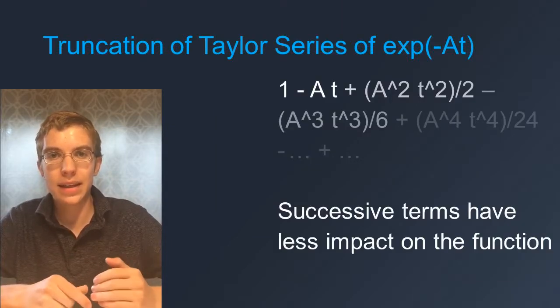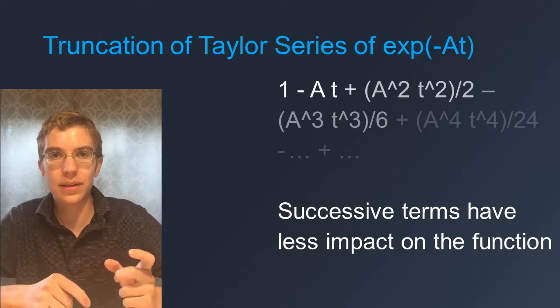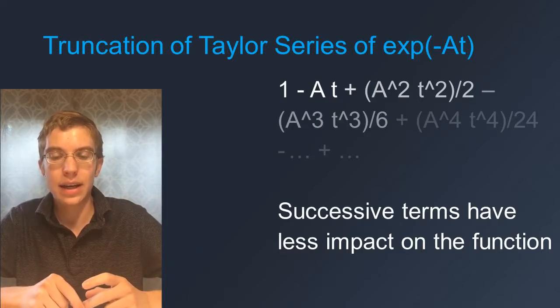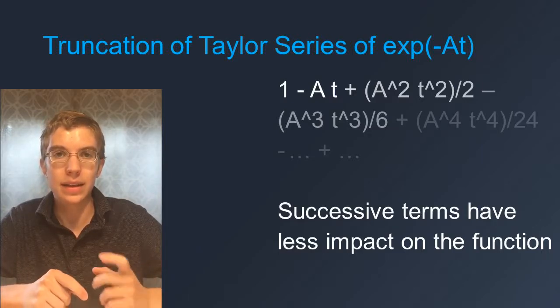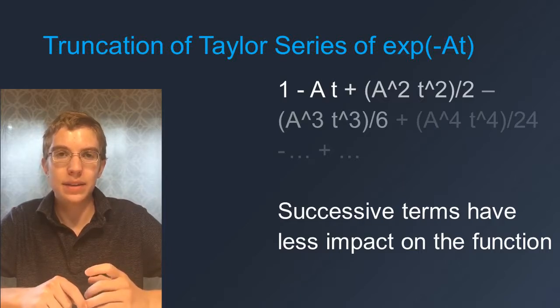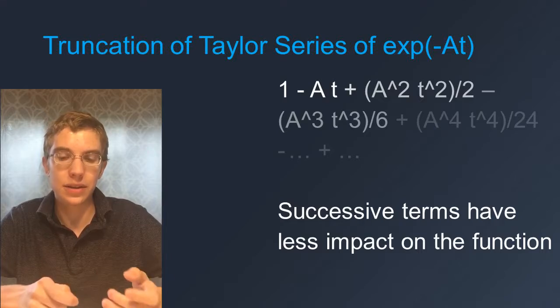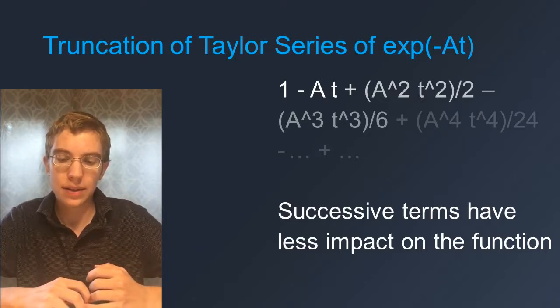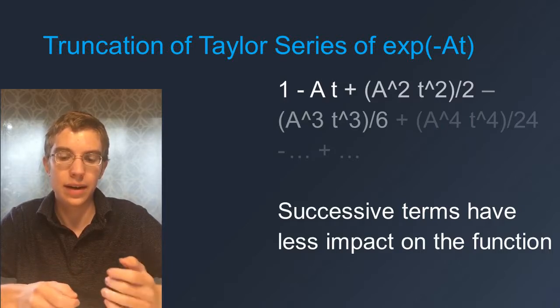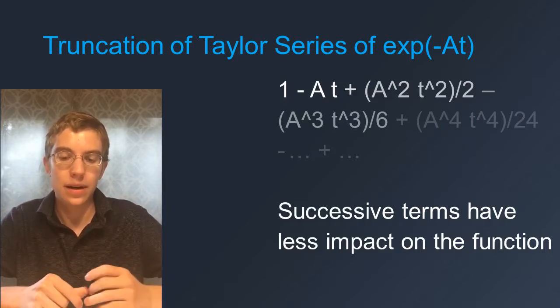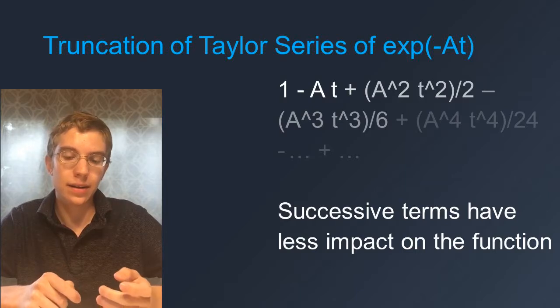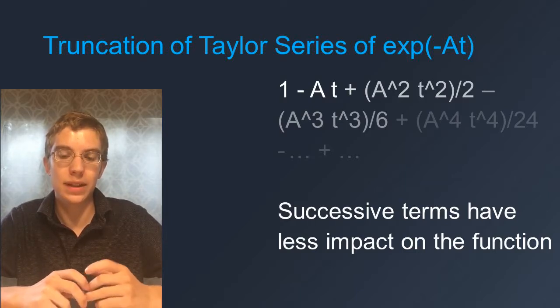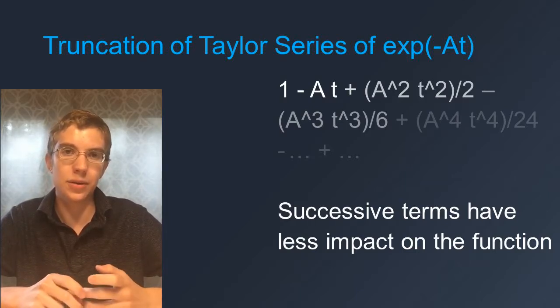The decay that happens in between the periods of the voltage of the rectifier can be modeled as a linear approximation, and this is just gained through a truncation of the Taylor series. So in summary, the internals of the system, such as the voltage threshold of the diode and the response of the capacitor, combine to form a nonlinear yet time invariant system which converts an AC signal to DC for use by a device. Thanks.